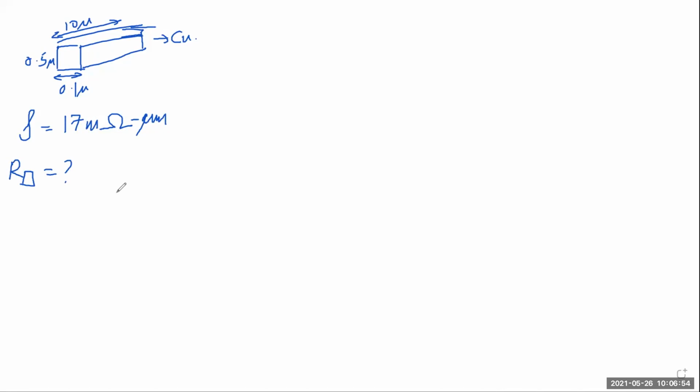Okay, Sundarani says resistivity by height. Good, so 34. Also give the units. So 17 milliohm micrometer by 0.5 micrometer. The micrometer cancels, and this is 34 milliohms, right?